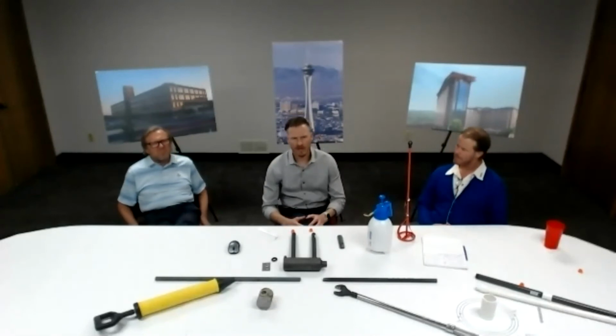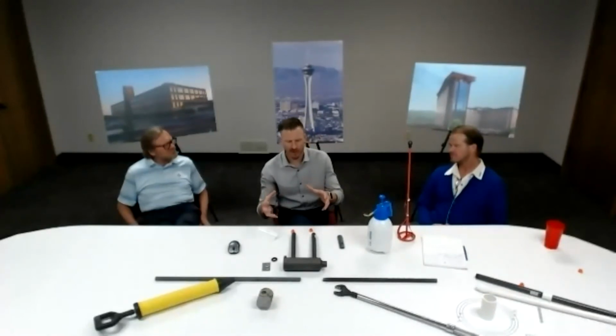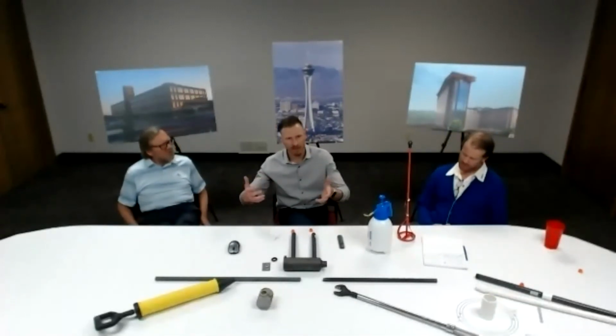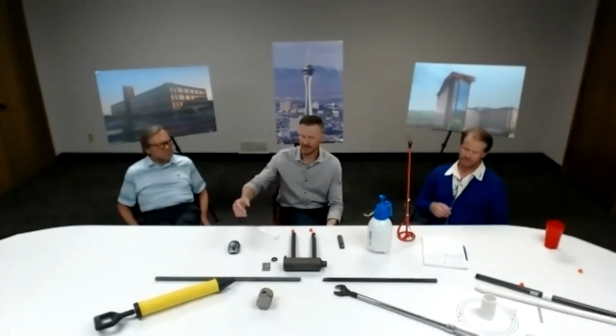I was going to add something to that, because if we were able to work with the engineer of record and figure out what those forces are, you can always add couplers and add more steel. Depending on how many number 10s you have, we could substitute some different size bars to get the same strength requirement through that section, where we need it.